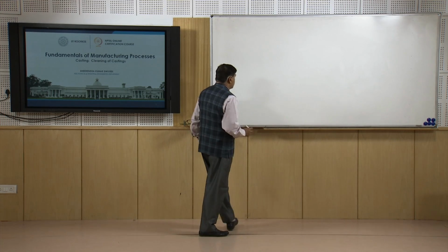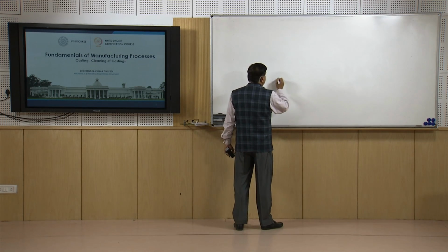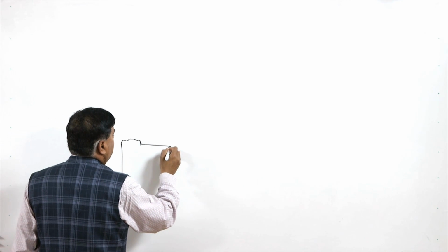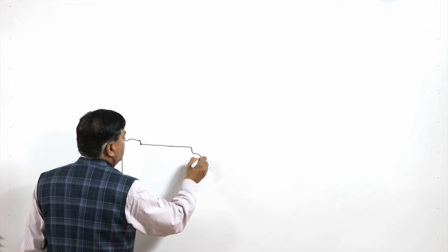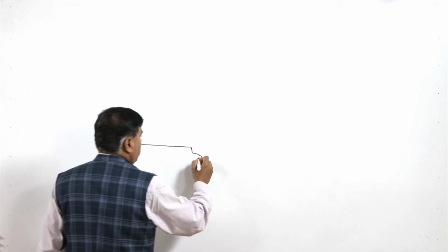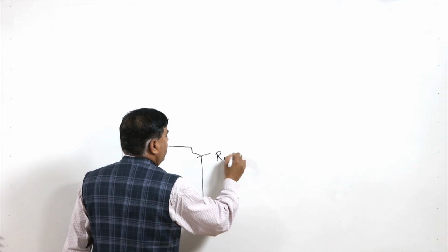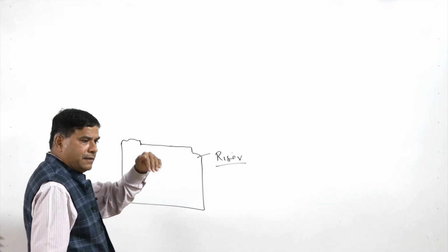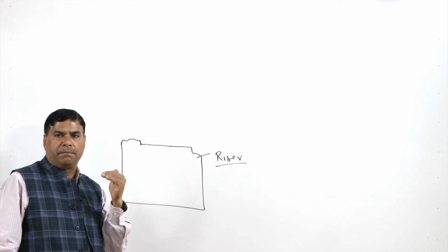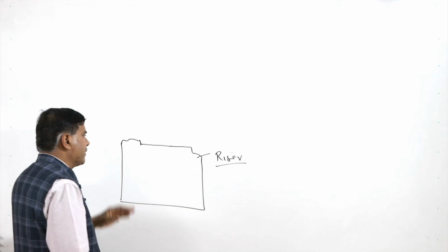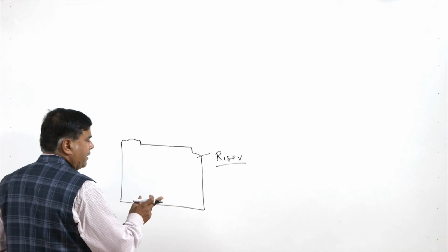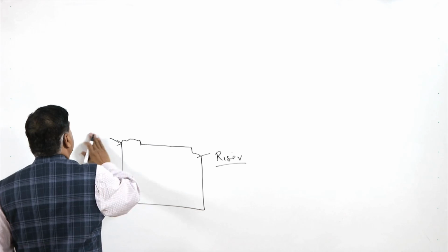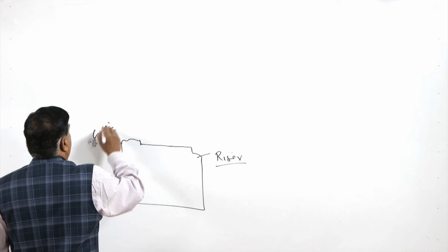So, like say in the casting, this is the section where cutting has been done in the casting, and this is the section where cutting has been done to remove the riser. So the riser, either if it is of cast iron, hammering would have been done, or if it is steel, then either flame cutting or the band saw or hacksaw, whatever has been applied for removal of this, or the parting off with the grinder, and this is where the riser gate was there.